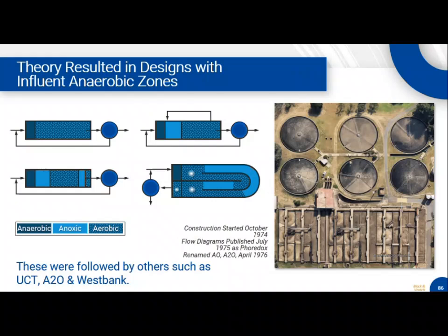If it just stays. All right, how about this one? So now we have this anaerobic condition, and then there's this anoxic condition, right? And there's a mixed liquor recycle pump, we call it, that's bringing the nitrified mixed liquor back into this zone, and it's kind of wrapping around here. And the RAS comes right into the front end of the anaerobic zone.